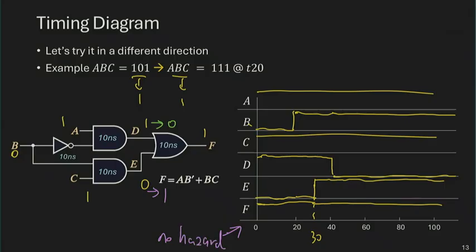The very same 2 input patterns. You go from 111 to 101, you have a static hazard. 101 to 111, you do not have a static hazard. And this tells us that hazard is a directional behavior. It happens only under some limited directions when that hazard variable changes. Right. Does anyone know why we do not have a hazard in this case? Right, based on the circuit diagram. Any intuitive explanations? Why does my output remain a 1 when B goes from 0 to 1?